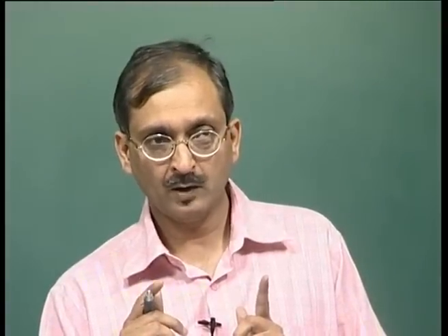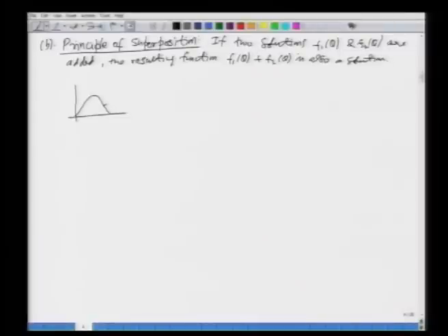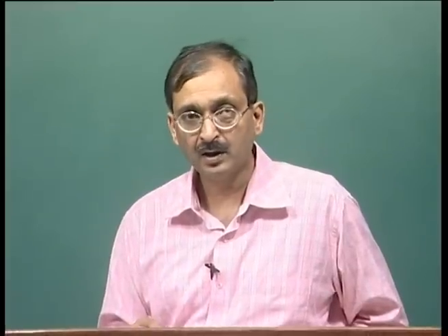It could be 1 centimeter or 1 inch or 1 millimeter. So, from 1 centimeter of rainfall, if it is applied uniformly with respect to time and space on the catchment, what will be the direct runoff hydrograph? That is called your U or the unit hydrograph. So, this is your time and this is your DRH response. This curve is the direct runoff hydrograph response due to 1 centimeter of effective rainfall applied uniformly over space and time on the catchment.